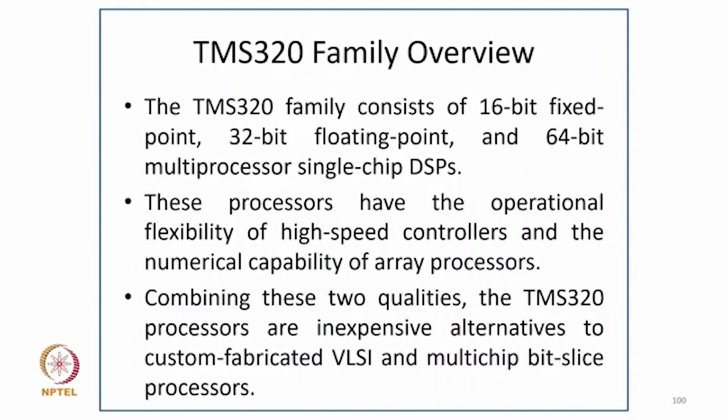Coming first to the TMS320 family overview. The TMS320 family consists of 16-bit fixed point, 32-bit floating point, and 64-bit single chip DSP microprocessors. These processors have the operational flexibility of high-speed controllers and the numerical capability of array processors.